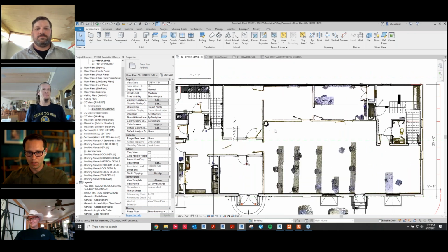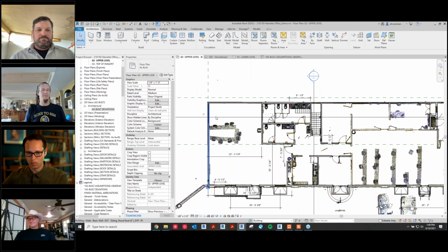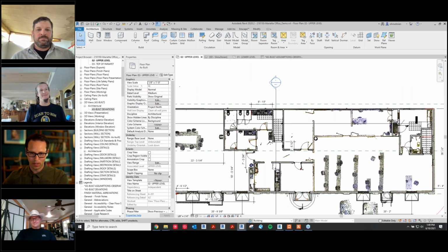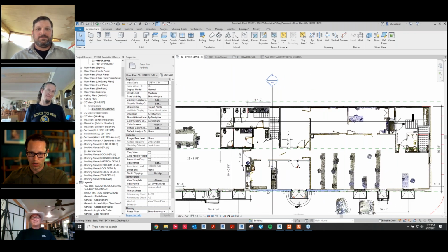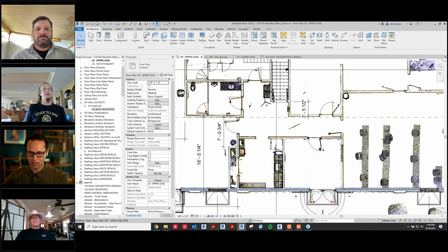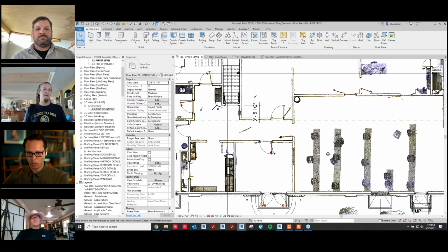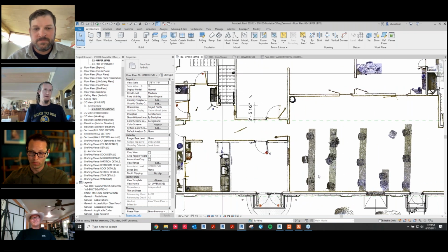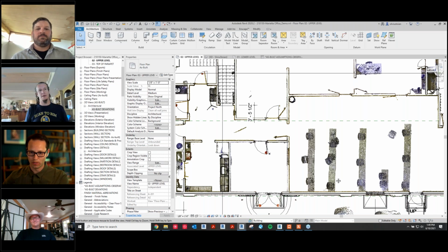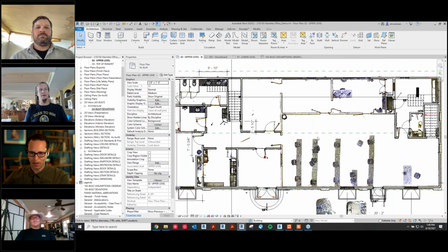This building, instead of being rectangular, is actually a parallelogram, and the walls are leaning in. There's some sort of pressure on the foundation walls that forced them to lean in about 4 inches, which pushed and deformed the entire building.